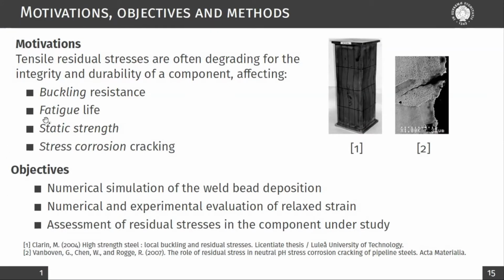Generally speaking, residual stresses, and in particular tensile residual stresses, if not intentionally introduced, can reduce the structural integrity of a component in different ways. They can decrease the buckling resistance, the fatigue life, or the static strength of a component, as well as give rise to stress corrosion issues. For these reasons, the following work is intended to investigate the residual stresses in a welded specimen.